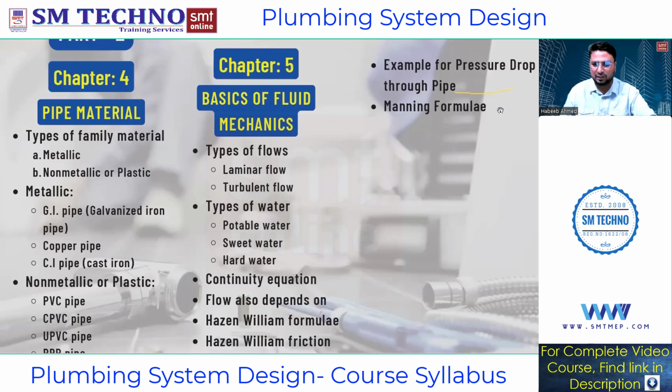After that, we'll see the Manning's formula. This is used only on the drainage side, and it is an approved formula from IPC. Remember this. Hazen-Williams is used on the water side. So this ends part 2 in module 1, that is, the water side.